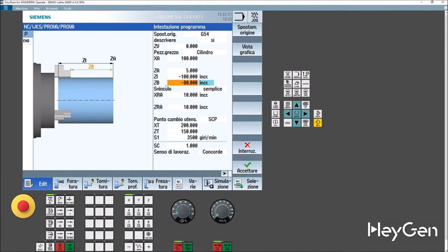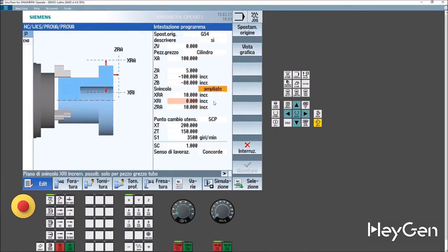The overhang is now used. The overhang of the part from the jaws, and this is interesting with ShopTurn. You can't go around the jaws because the machine, if you've entered your data correctly, stops. Release. Here it is. Pay attention. The release is important. Simple. Expanded. All of them.